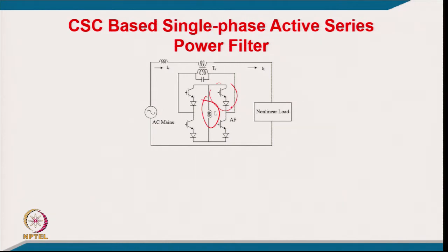So, you can call this a total bridge, and you need this capacitor as well. The current will be PWM kind of current generating the voltage, so you need this capacitor also. It will be providing virtually the voltage compensation in series.